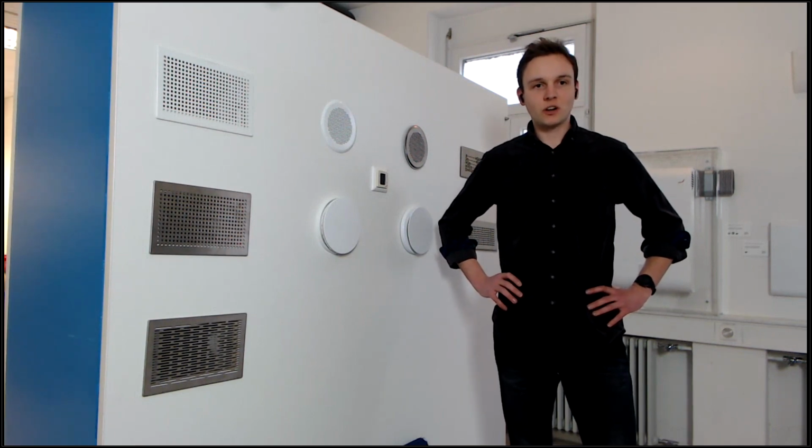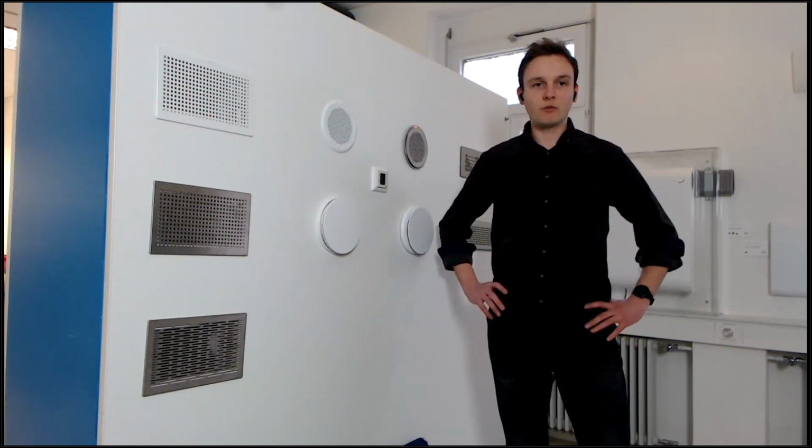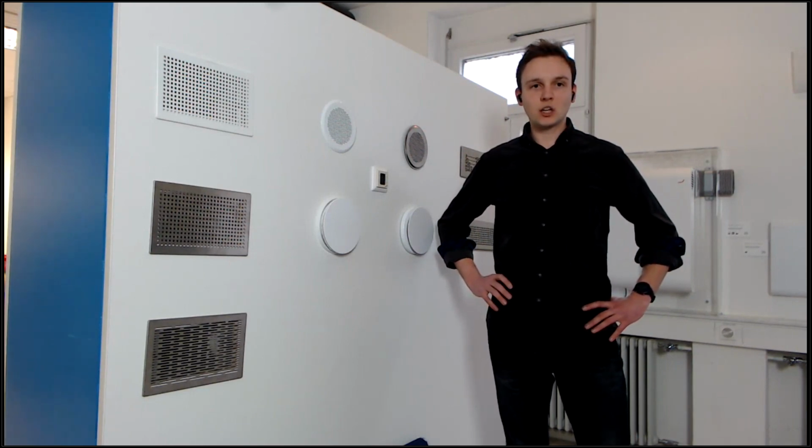Or did you ever think about why there is no switch on or switch off at our units? There are two reasons for that. Firstly, it's very important that there is constant air exchange when you have very airtight buildings, because otherwise you get humidity problems, and this could also end up in the spreading of bacteria or viruses. So even if you are on vacation for 2 weeks, you should not shut down the unit, set it on the lowest fan speed, which is the absent mode.